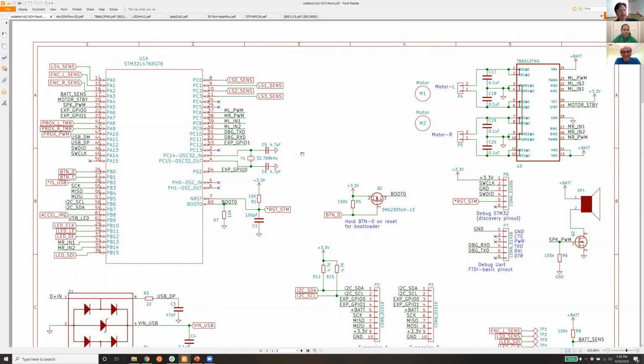But yeah, there's 5 infrared. There's actually a lot of infrared on here, right? There's the 5 photoreflective switches, those QRE1113s, and there's 2 of the Vishay, the really kind of super fancy Vishay sensors for distance, and they can measure approximate distance out to a couple of meters if you're lucky. We go into that a little bit, and there's a discrete emitter here, and that's the thing that you can really power up and get a very bright long distance light on that as well. And the other infrared stuff on here are the wheel encoders, which also have infrared LEDs that shoot across and make a photo interrupter.